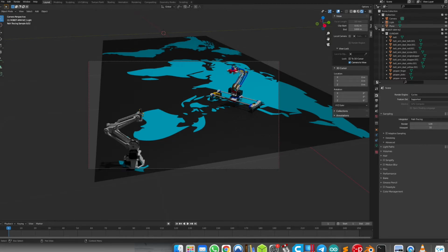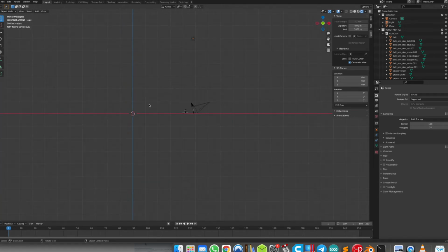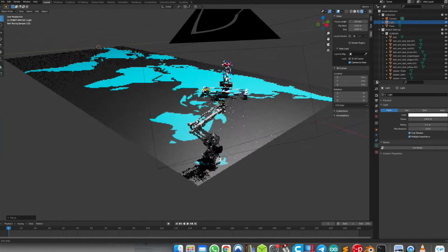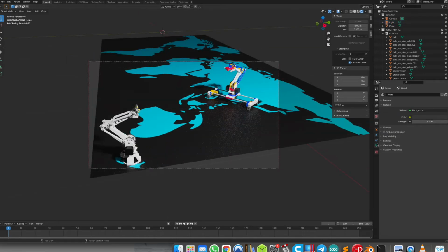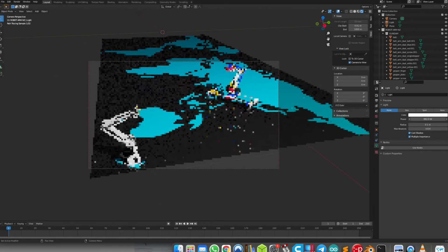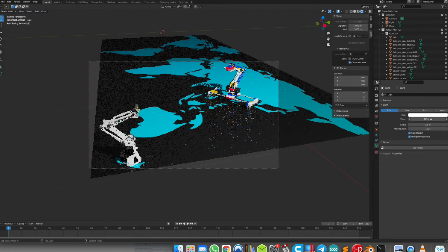We can change that. By zooming out of the screen, we can find the icon of the virtual light. There it is. We can select it and then press G to move it around the same way we moved with STL files. With the light object selected, we can go into Object Data Properties, which is the green light bulb button on the column of icons. Then we can adjust the power of the light source. The more the wattage, the brighter the scene will be.